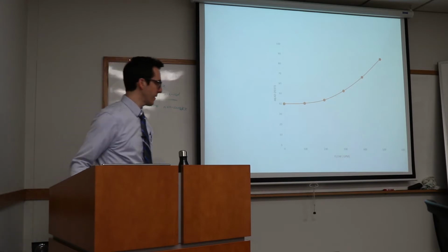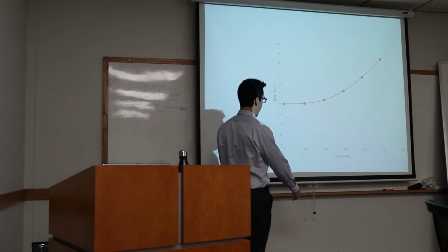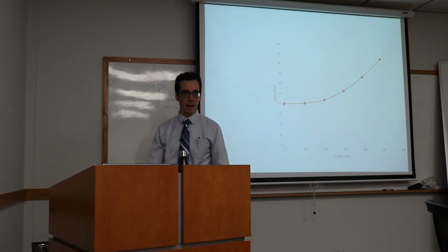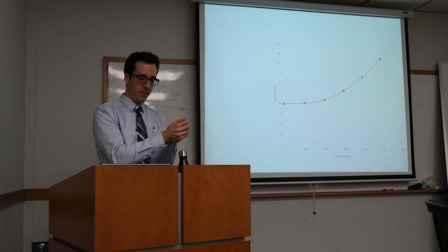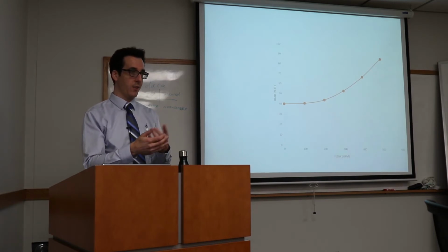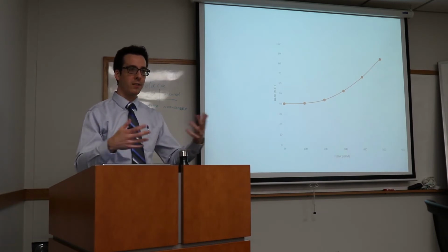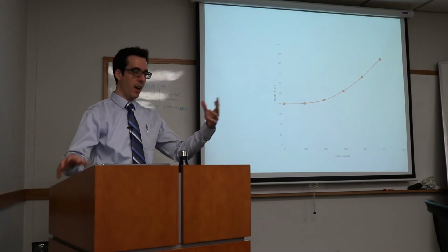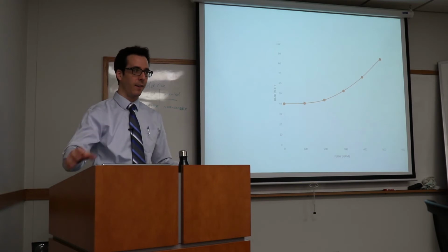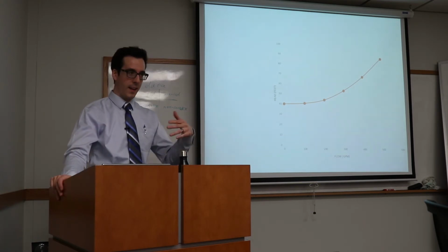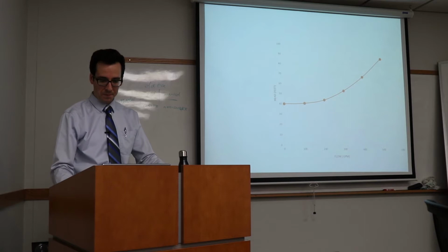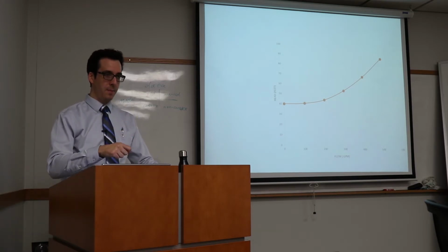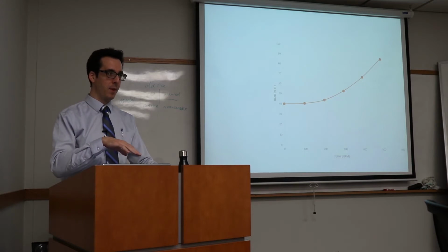So this tells us that if we want to design a pump for a certain flow rate, we know how much head to expect. We can usually develop these kinds of system curves from a hydraulic model. It's a computer simulation of the water system. It's kind of like Google Maps for water distribution. It knows the connectivity and the speed limits and all the different things. And we use that to produce this system curve. Okay, so you're part of a design team. So put your initials at the bottom of the page and pass your paper to the right.